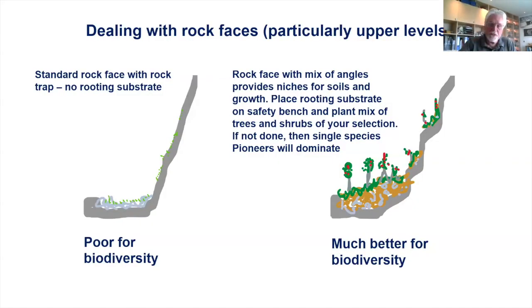So dealing with rock faces. Again, imagine you're quarry managers and I'm trying to encourage you to do a better job. On the left-hand side, a straightforward slope. At the bottom, this thing here, the toe of it is a safety feature to stop rock tipping off the side of it. And you'll get some growth in there over time, for sure you will. But if you can put some rootable material behind that safety feature, and if you make some nooks and crannies up along the rock face, which will trap some sort of subsoils and whatever, it's going to go green and be a lot more interesting a lot earlier. Okay.